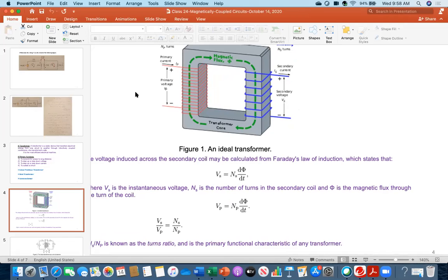Now everybody see, if you apply DC voltage here, can you write this equation? No, because if you apply DC voltage, flux will be produced, that is true, but that flux does not vary with time. You know that DC is independent of time, right? A DC circuit is independent of time. Only an AC circuit is a function of time, like V equal to Vm cosine of omega t. But in a DC circuit, it is based on the DC voltage. It is time independent. So the DC flux cannot vary with time.